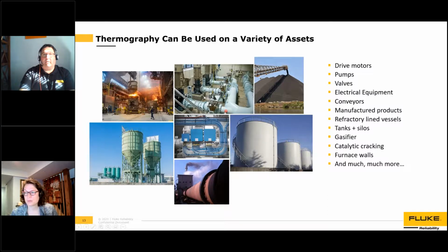In a situation like the center photo here, we are looking at pumps and electrical motors. This may be an application where you would have a pan and tilt centrally located looking at all 4 of the pumps and motors simultaneously. Again, going to the multiple areas of interest, it can pick up multiple areas on both the motor and the pump simultaneously. And with a pan and tilt system, you can change the areas of interest per view. The areas of interest for this pump and motor could be different than for this pump and motor, because this is moving and rotating, so you may have to move them or align them with different areas.